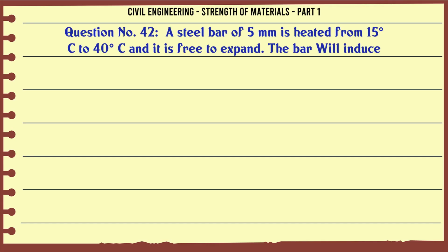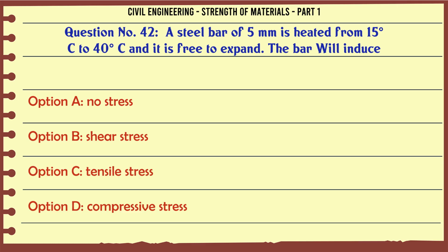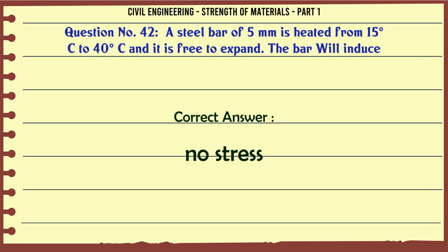A steel bar of 5 mm is heated from 15 degrees C to 40 degrees C and it is free to expand. The bar will induce: A. No stress, B. Shear stress, C. Tensile stress, D. Compressive stress. The correct answer is no stress.